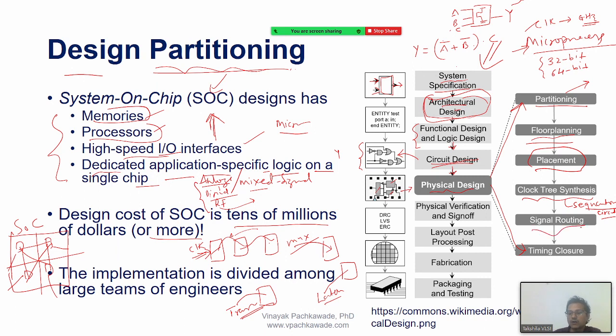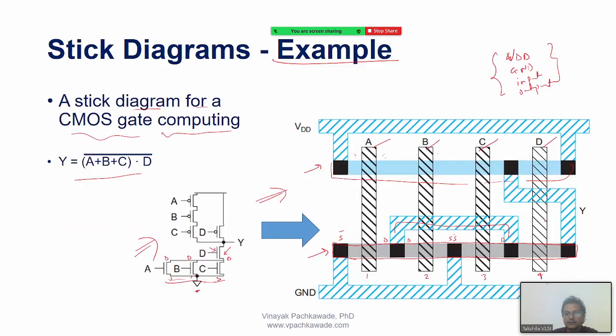Then signal routing. What is signal routing? Once I have NMOS placed and PMOS placed, I have to draw these metal layers. Poly is already done there, right? All these metal layers, and I have to optimize the layout for the area and the dimension, but the tool will take care of it. But as an engineer, I have to understand how I can still optimize. Once the tool does the auto routing, it is the engineer's job to closely inspect each cell for its placement and then adjust a little bit here and there.